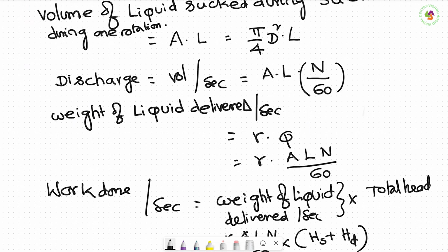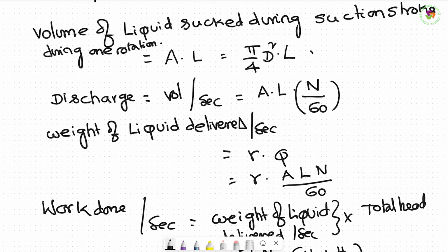Once again, where is the crux of it? This is very simple. But the second point, this you need to think. What I told is the volume sucked for one suction stroke is this much. How many rotations does it make per minute? N. Per second, how many rotations does it make? N by 60. So how much is the volume flowing per second?